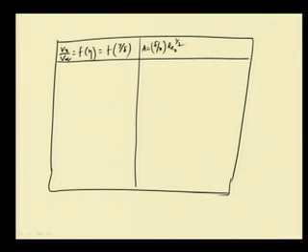We have seen that delta by x is equal to some constant into Re x to the power minus half, and we are trying to see how much this constant comes. The other one, B, is another constant, with respect to CD into Re x to the power half. We have seen that in both cases, if we take a different velocity profile, the functionality remains the same with Reynolds number to the power half, but the constant value does change, and we will see how it changes.